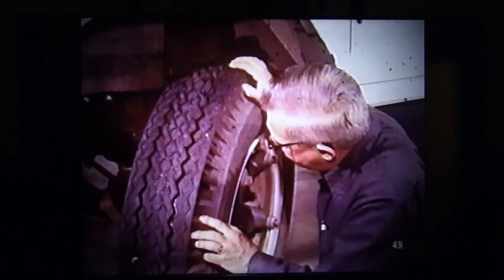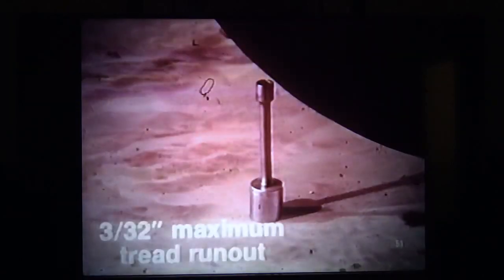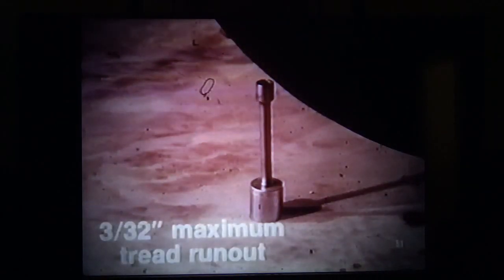After you are certain the steering linkage and bearings are not the cause of the disturbance, check all the tires for chunking and signs of ply separation. Check all the wheels for cracks or damage to the center sections or rims. Next, check each tire's tread runout. The runout should not exceed 3/32 of an inch. Then check the lateral runout at each tire's sidewall and outer rim edge. The maximum allowable side-to-side runout is also 3/32 of an inch. Retorque or replace any wheel tire assembly that is out of specifications and road test the vehicle.